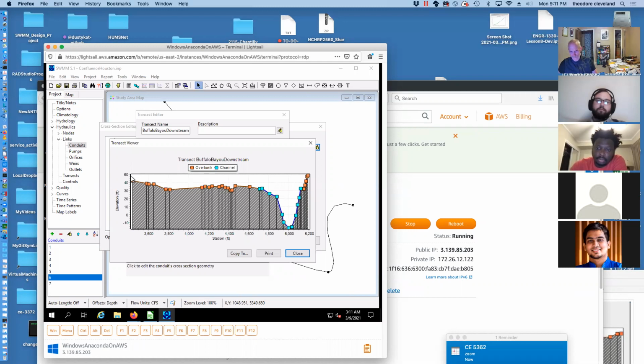If we started getting results that the state of the water surface was maybe at 48 feet, when we look at these sections, we'd realize, well, if it's 48 feet, it's trying to spread to the left. We've either made a big mistake somewhere else, or the cross section needs to be relaxed and extended.